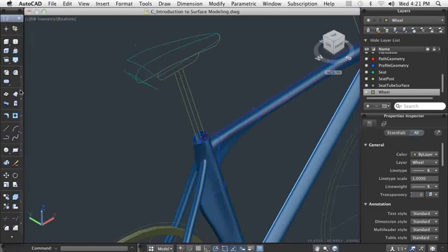Finally, I'll create the seat surface by sketching in the geometry edges of what I want it to look like. Then I can use those edges to network them into a surface. Here, I only need to know what I want the object to look like by drawing in the boundaries, and then I let the software do the work for me.